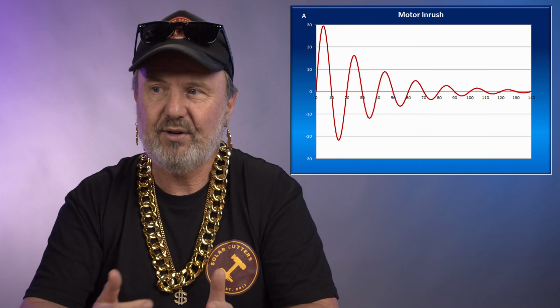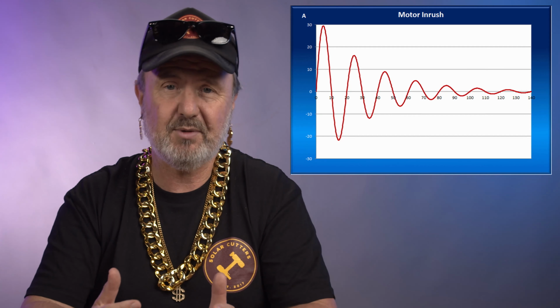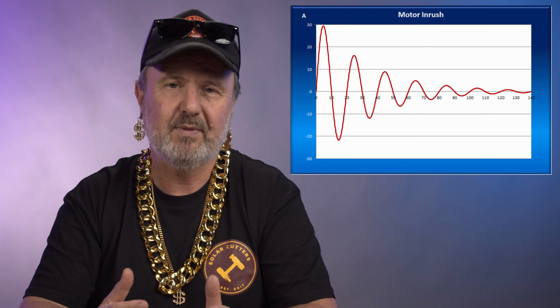But for many, a pressure pump is the problem load. It will often draw 3, 4, 5, up to 7 times its run power as it starts. So now from a maximum demand calculation perspective, we need to consider not just the coincidental maximum demand of loads, considering power factor, but also considering surge demand. So how do we break this down?